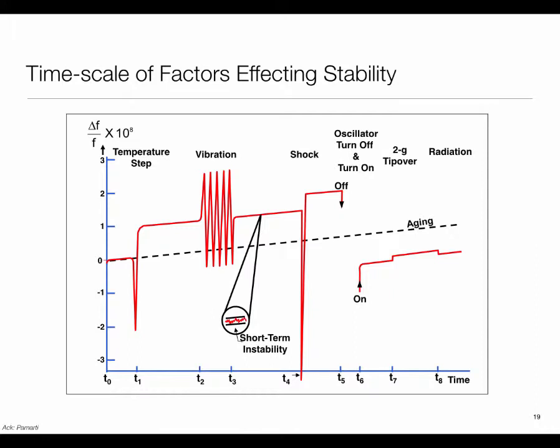Then you may have issues like the oscillator being turned off and on. It's not like when you power something on, it instantaneously reaches its good frequency value. It takes some time to stabilize, and that in itself would be milliseconds. So one has to design that carefully also. And then there might be a long-term trend because of the aging. So all these factors come into play, and the bottom line is that the clocks that you work with in these systems are not perfect.